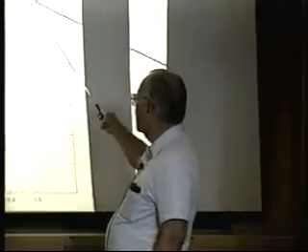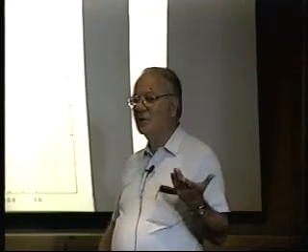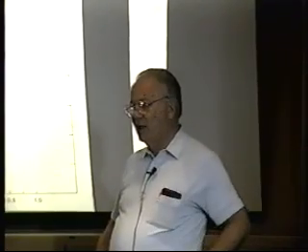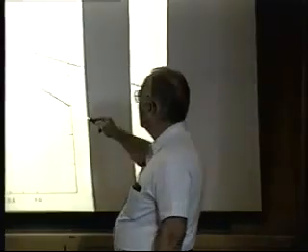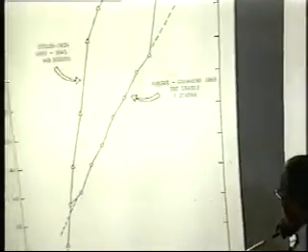In 1969, Ramsey and Guerrero, I think this was a master's thesis at the University of Tulsa, wanted to see through selecting 202 leases, which they judiciously selected so that there was no additional drilling going on at the time on any of the leases. That'll screw up your interpretation. None of the wells were producing water. And they come out with a slightly different distribution than the original Arps, but still in no case was there a B value in excess of 1.